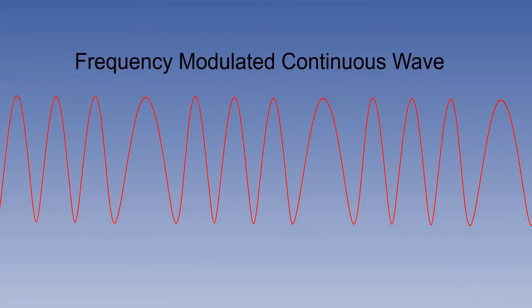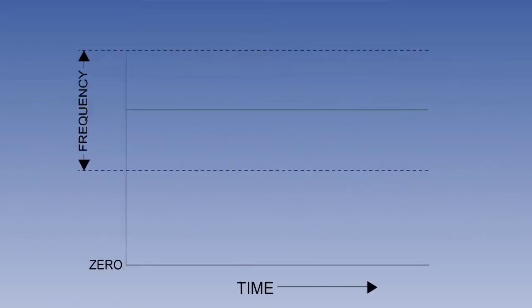With this type of modulation, we have a continuously changing characteristic of the transmitted signal, and therefore we have something to compare the received signal against and to measure the time difference. We'll now see how this is done. Consider the transmitted signal at some particular point in its frequency modulated cycle. Let's assume that, on our graph, it's passing 4,300 MHz on an upward slope. The radio wave travels down to the ground and returns sometime later as a received signal, still at 4,300.